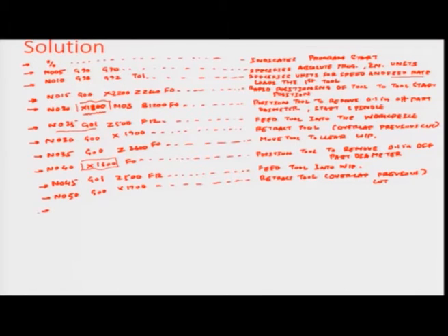Go back again into the start position so that you can clear off along the Z axis also. Z 2600 is written as G00; you do not even need to write G00 here, since G00 has already been programmed in the last step. Give a 0 feed in this particular case, and this corresponds again to move tool to clear workpiece.